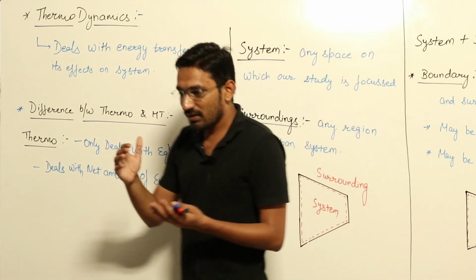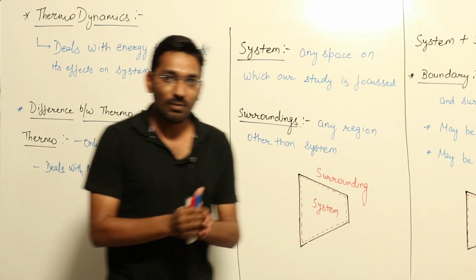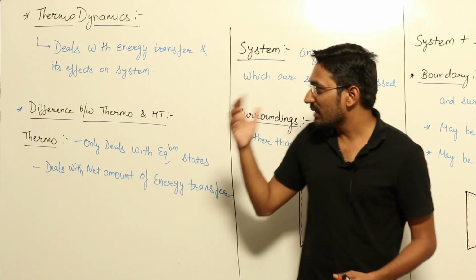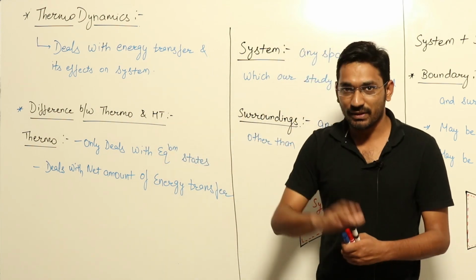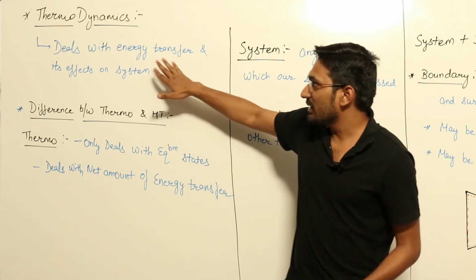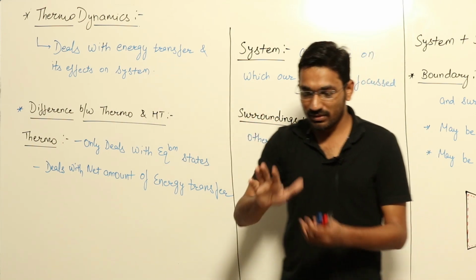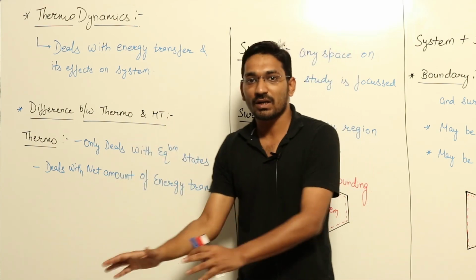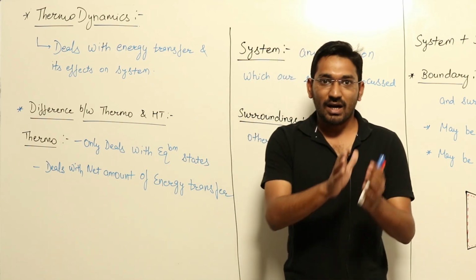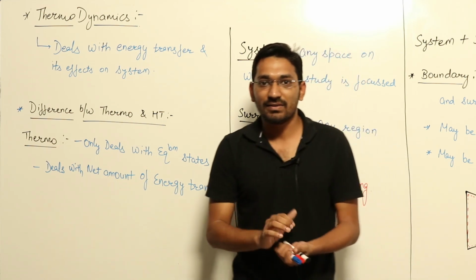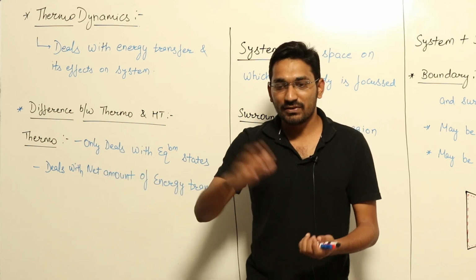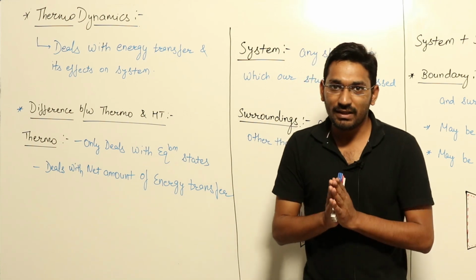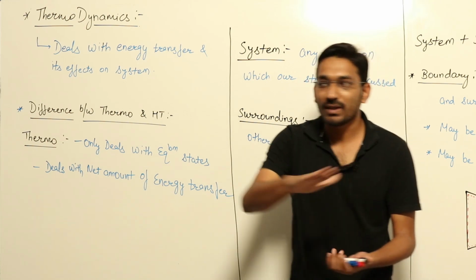Now there are two subjects in your thermal engineering. One is thermodynamics and one is heat transfer. If you ask what is the difference between thermodynamics and heat transfer, first of all let me clear this. Thermodynamics will tell you the amount of energy which is transferred from one system to another system. If I have a cup of water which is at 100 degrees Celsius and after some point of time its temperature decreases to 10 degrees Celsius, thermodynamics will tell me how much energy comes out of the water, from that system, going from 100 degrees Celsius to 10 degrees Celsius.